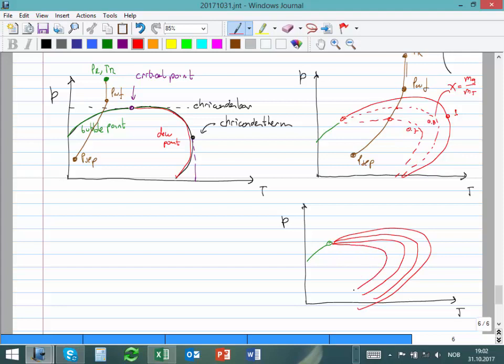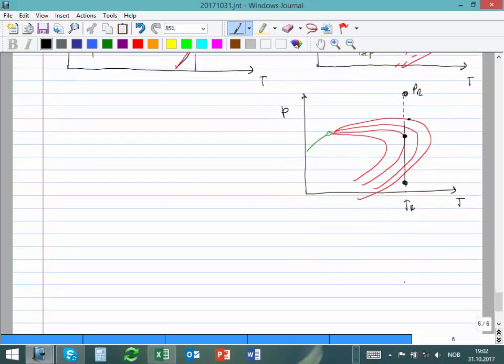That means that if you start here, at your reservoir pressure, and it starts to decline, up to this point you will start getting liquid and more liquid, because you go from 1 to 0.8 to 0.7. But then if you continue going down with pressure, in the end you'll start to revaporize, which is very strange, until you might end up with pure gas again. So that's called condensate, or retrograde condensation.